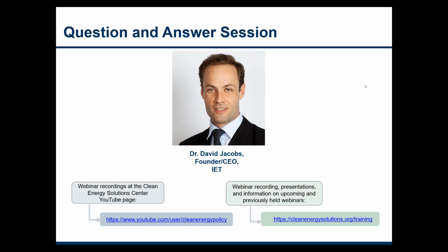Now the net FIT program, which has been discussed in South Africa and which is also currently being developed by selected municipalities in South Africa, is really a feed-in tariff which incentivizes self-consumption by paying very low tariffs for any unit that is fed into the grid. I think they were talking about excess electricity fed into the grid at a rate of 8 or 9 cents per kilowatt hour. So you really have an incentive to first of all optimize your self-consumption, and then only the excess electricity that you have is fed into the grid at a relatively low feed-in tariff. So it's very similar to many feed-in tariffs that we have in Europe, so that the feed-in tariff payment is significantly lower than the retail electricity price, but still higher than the wholesale electricity price.